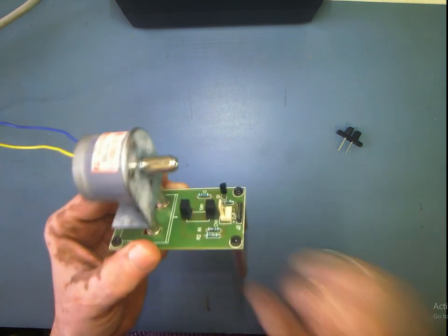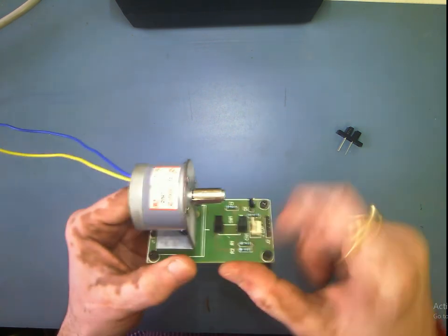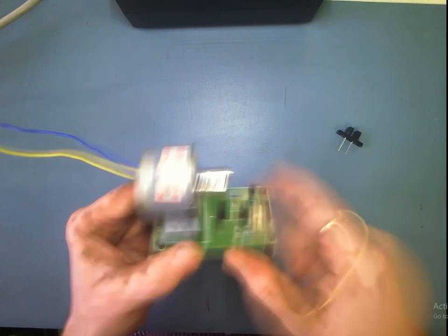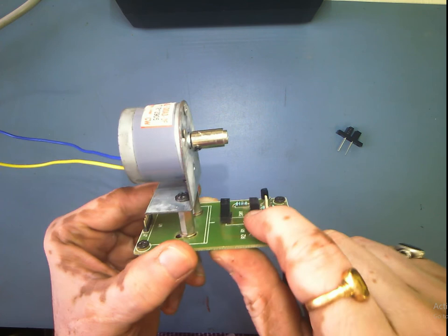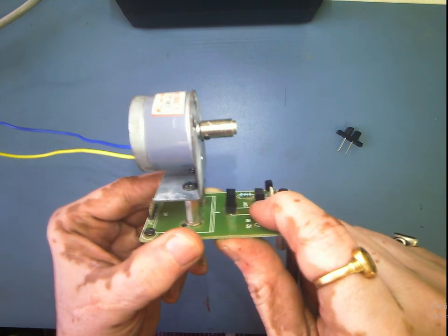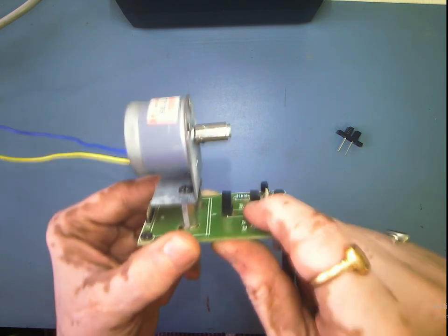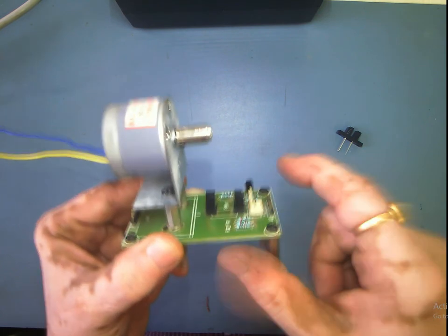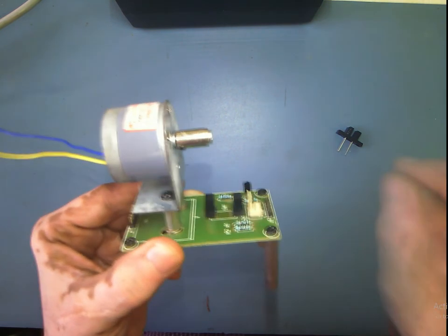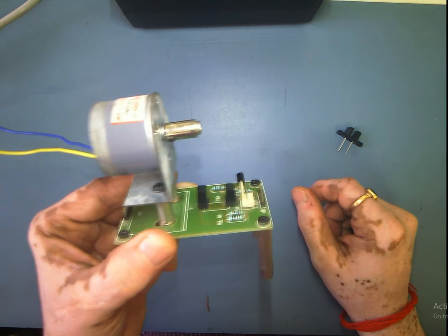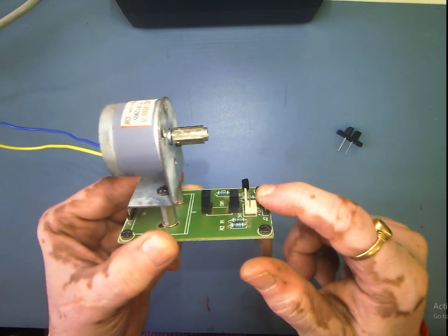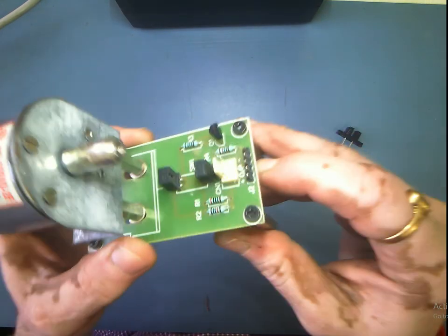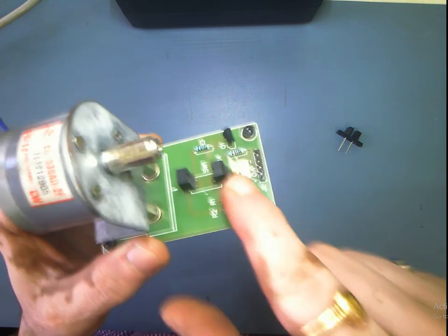of this shaft. There is a very simple electronics over here, and this is the slotted optical switch. These two housings you can find. This is the slotted optical switch that we are actually employing here to generate a frequency signal. As the shaft rotates, a frequency signal will be generated at the output pin. You can see there is a connector. A 3-pin connector is given.